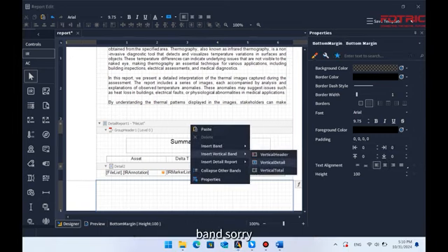And I start building based on what I need. So I want the digital image first because that's what I want my customer to see. So I want it in this section, not the other. Okay. So that's the main part that I want him or them to see. And create a little bit more space for the infrared image now. So the infrared image will go here. And you can see that when there are overlaps on the image, they will show in red. So I just need to readjust those two.